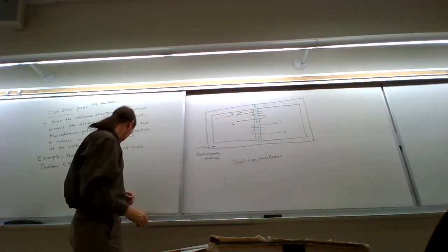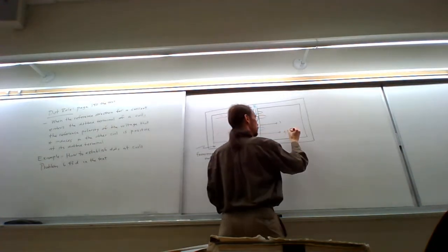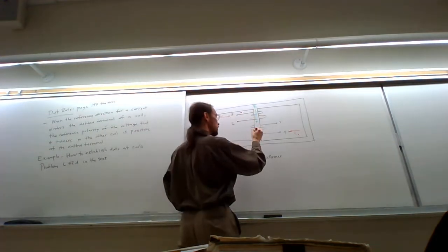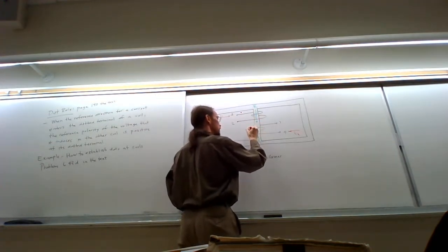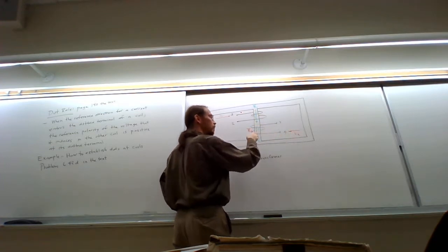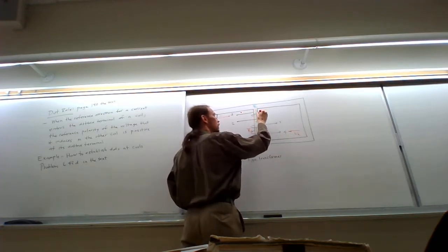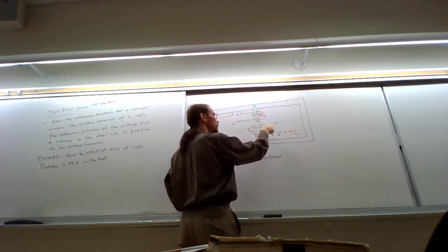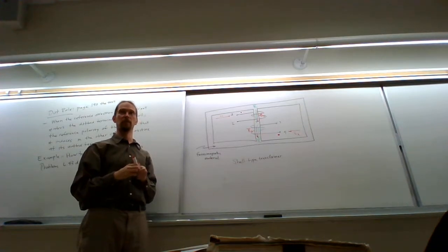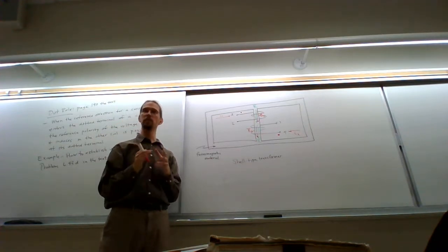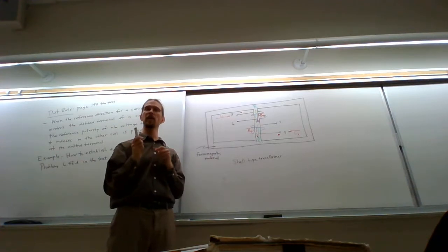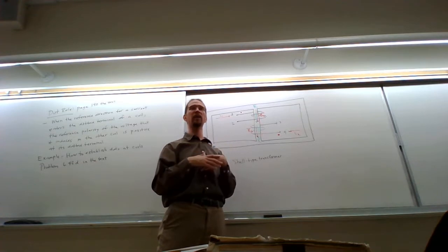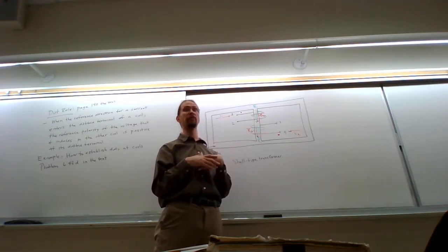So if I had this current, let's say I2, going into there, on the inside of this, the magnetic field produced by this current would be going in the same direction there and the same direction there, which means that this terminal and that terminal happen to be dotted. Right? So it really has to do with superposition, finding the magnetic fields depending on where you feed in the current and making sure that they add up to something bigger so that you get a larger magnetic flux.